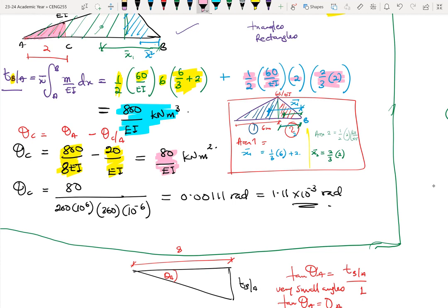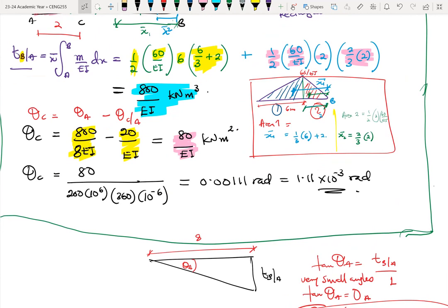All right. I think we're given the values of E and I. So we can put them into the equation. All right. Make sure that the same units are being used throughout. That is the most important. Okay. So the top portion will mostly be in terms of kilonewtons and then also in terms of meters. So your E should also be in terms of kilonewtons per meter squared. And your I should also be in terms of meter 4. All right. So at least once they all have the same units, then you know that you're on the right path.